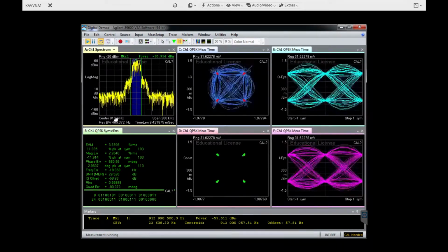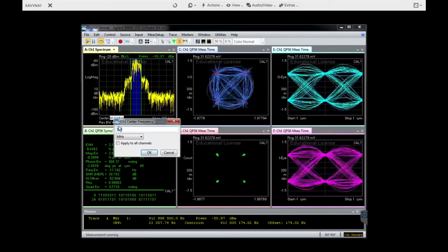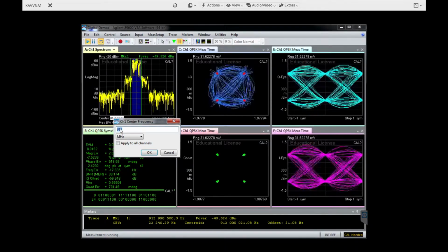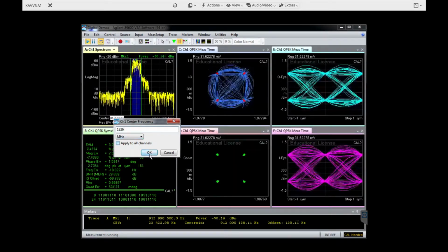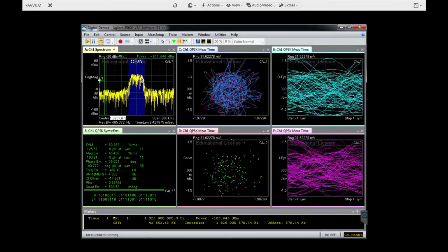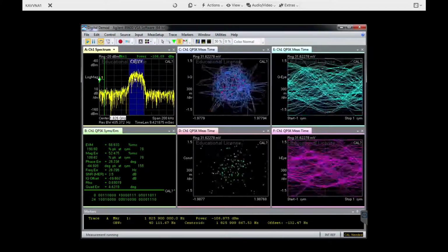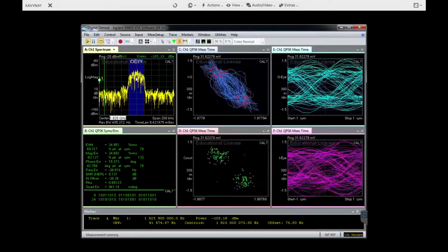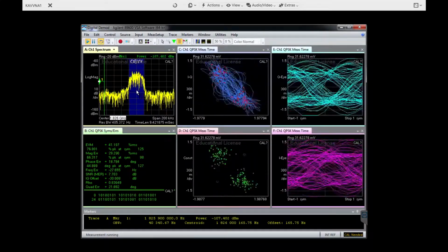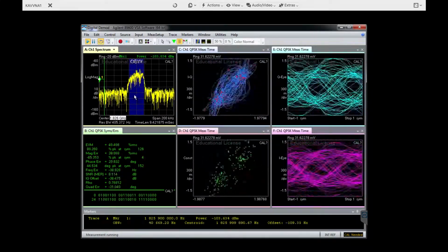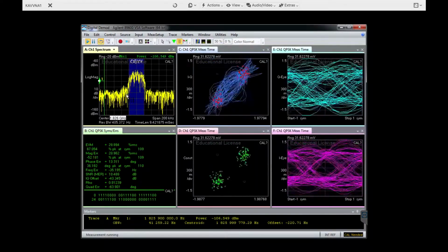We can also see the second order, which will be in the next harmonic, which should be at 1826 megahertz. So you can see now here we are having another signal, which is a harmonic of the fundamental signal that we are transmitting, and this will cause interference to other users who are working at this particular frequency.